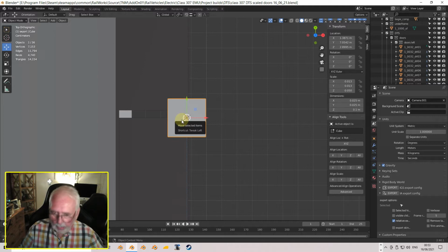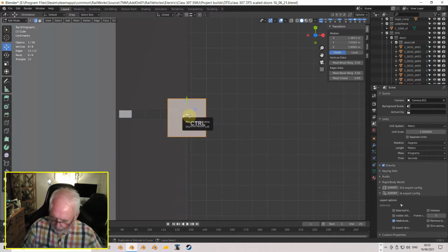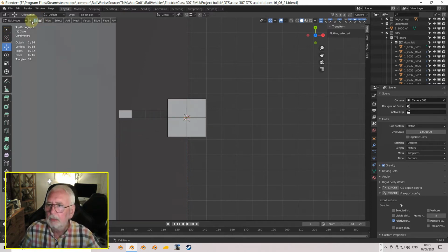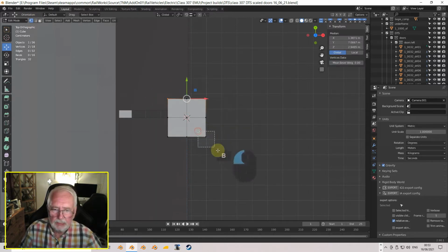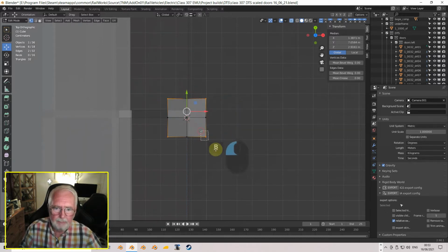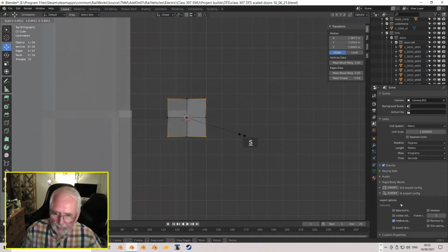Now what I'm going to do is go into edit mode. I'm going to do a couple of loop cuts, so one there and one there. There we go. Now deselect, Alt and A, go into vertices mode and select these corner vertices like that. Okay, and now we're just going to scale it till it looks sort of round. So scale, make sure we're going right the way through the model. So I'll just select these again. Okay, that's it, and let's scale now. There we go, that's sort of round.